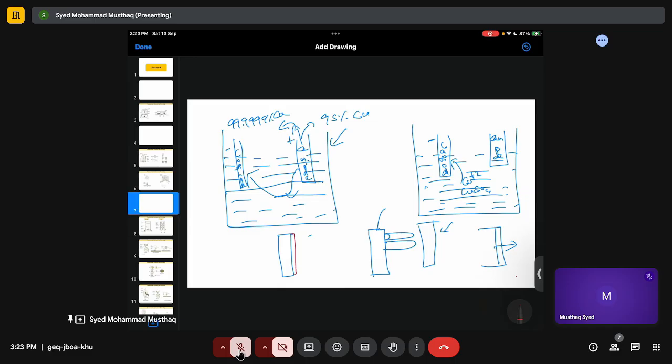This is at time t1. After time t2, the thickness has gone up by this much, and after time t3, the thickness is uniformly growing. But here it is not the case. Because the thickness is not uniform, these guys grow so large that they just touch the anode. So this was my cathode. They have grown so large that they actually touch the anode. Whenever the cathode and anode touch, that is nothing but a short. That means you have created a short circuit.